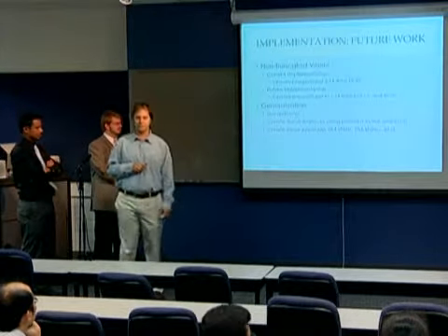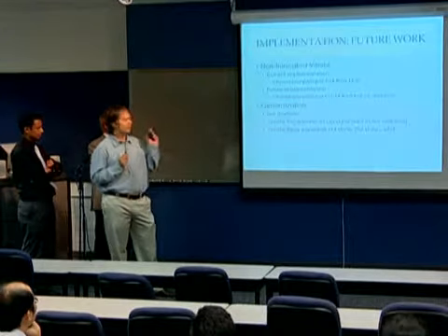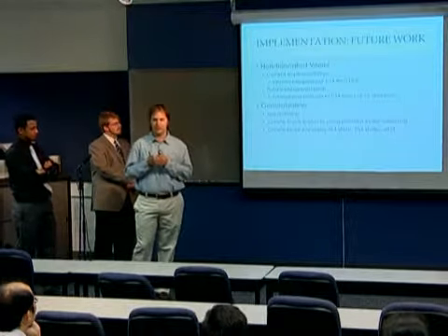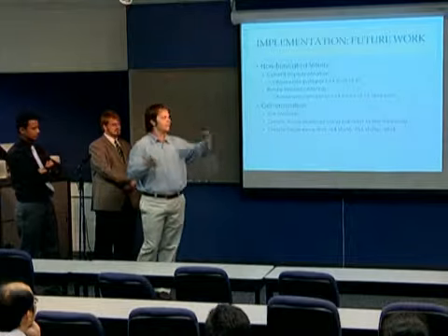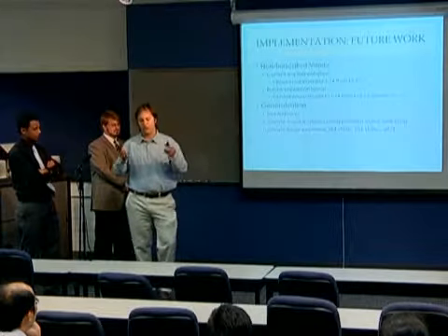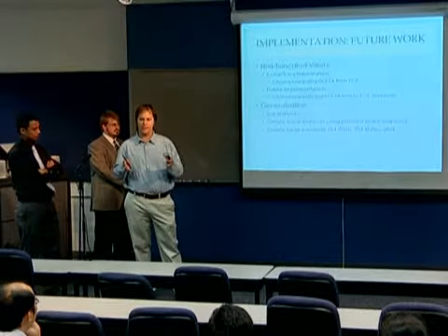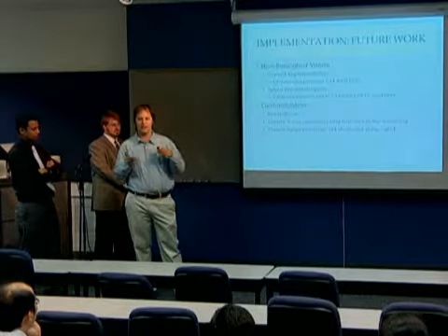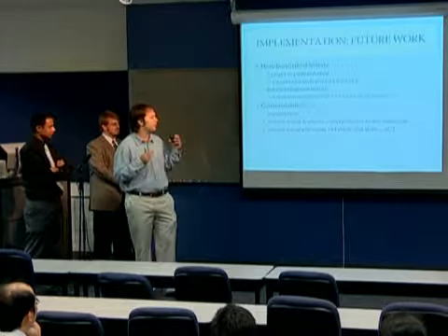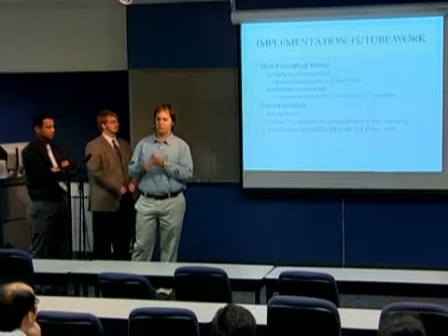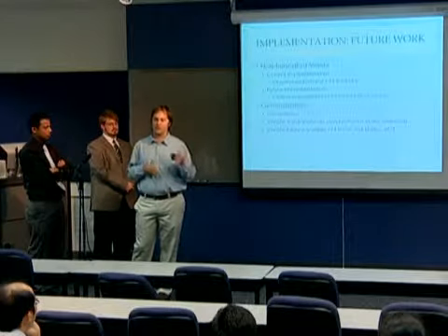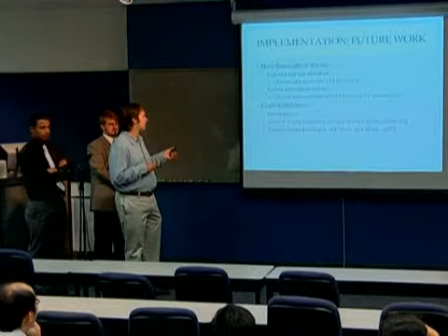So, future work for this implementation. We implemented the truncated Viterbi algorithm, which took 14 points. Imagine you're just calling each point on a big scale from 1 to forever. I took 1 to 14 and made a path decision based on those 14, and then I took 15 to 28 and made a path decision based on those. Future work could improve our algorithm by taking 1 to 14, making a decision, and then taking 2 to 15, making a decision, 3 to 16, making a decision. That's one improvement we could work on.